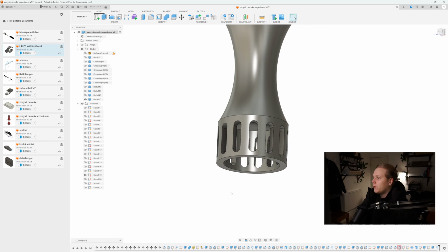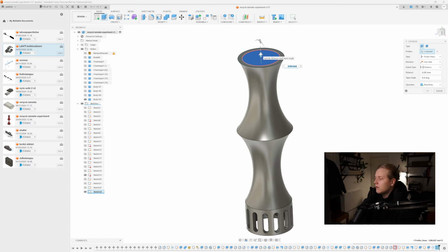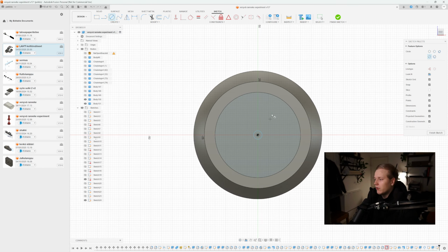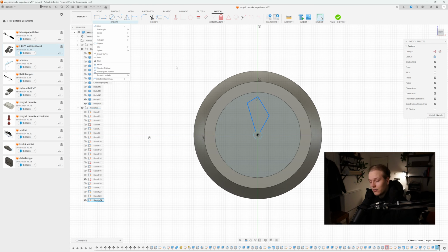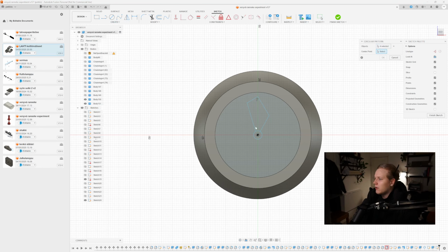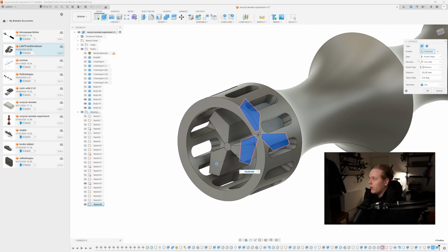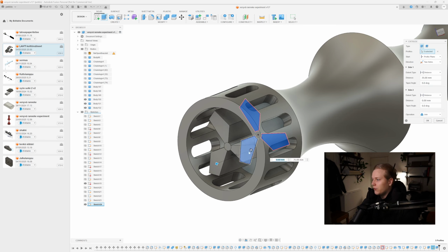The circular pattern one. Now we're gonna make a button on top, and if you want to make it a separate color for the render, at this point I'm gonna make it a new body instead of joining it. Then we're gonna design the blade. Then again, you can also use the circular pattern here on a 2D sketch. I've selected the objects we want to rotate, and we get the axis. And then when we're extruding, instead of extruding from one side, we can extrude from 2 sides, so we can make something like this a bit easier. Yeah, I think that is good.